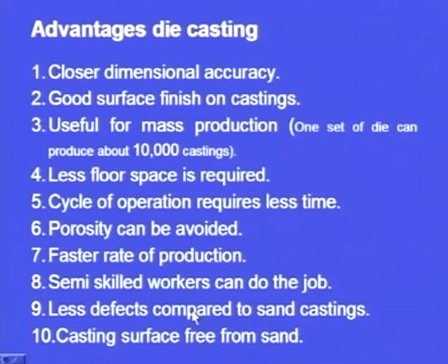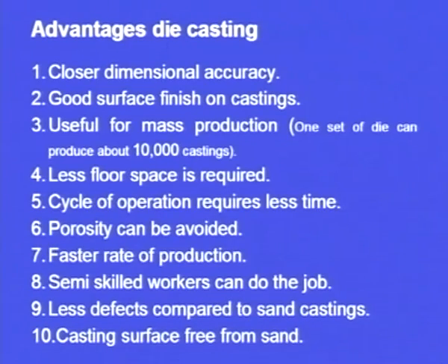And another drawback of the green sand castings is, after solidification is over, the sand casting surface will be having sand adhered to it, because we have cast it inside a sand mould. For that we have to clean it. But in the case of the die casting, the question of sand sticking to the casting does not arise. There is no sand mould, we are using a metallic mould. This is another advantage. So, it has got several advantages over the conventional sand casting process, yet it has got some limitations. Let us see the limitations.